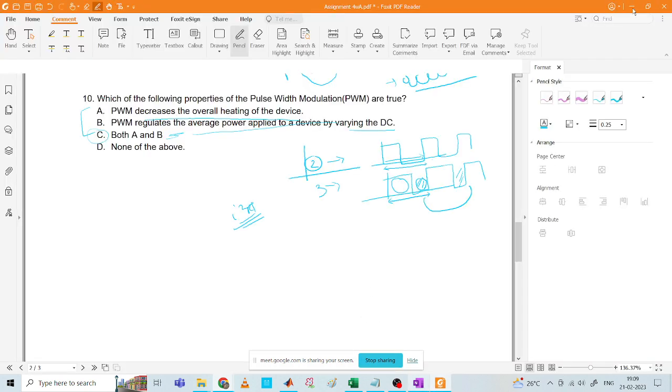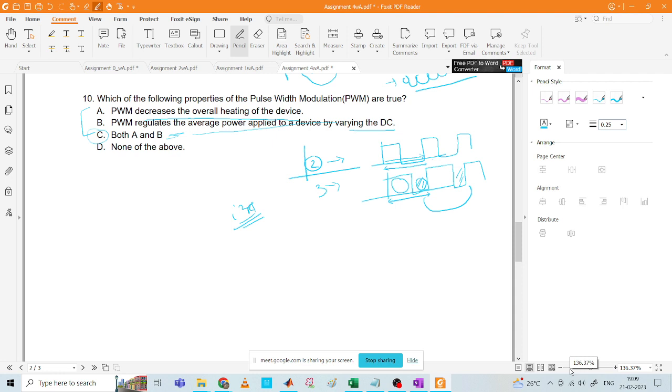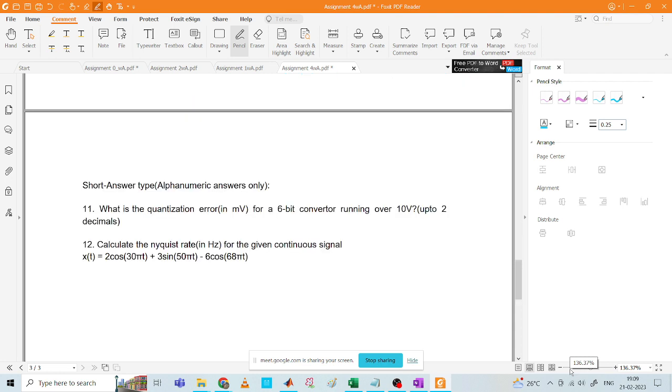Sir, do we have any formula which gives the relation between bit rate and baud rate? That depends on what kind of line encoding you are having. Without the line encoding, no one can tell what the formula is. It can be anything. There are cases where the baud rate is twice the bit rate, and there are cases where the baud rate is a fractional value times the bit rate. So without knowing the line coding, it is impossible to say.